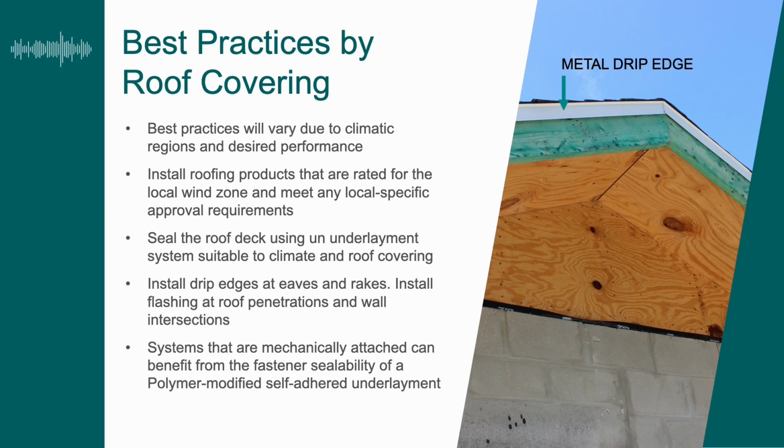And those best practices vary due to climate conditions, where you are located geographically, and the desired performance that you're seeking from your roof, how long you want it to last and under which conditions. Install roofing products that are rated for local wind zone and local specific code requirements.